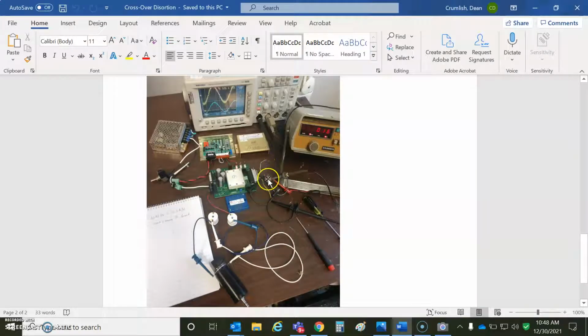I don't pull the gain scaler low. That'll add a little more crossover distortion, so I want to minimize crossover distortion here. And I'm just running from 24, but you could use 48, or on the 10 amp peak 5 continuous, you could use a 75 volt supply. I think this is the balance pot here to adjust the zero, given a zero at the input.